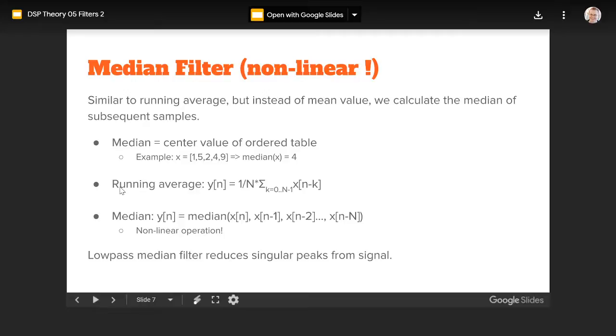Then use a high-pass median filter, meaning you take the original data and subtract the median filtered one with the correct time shift. The only things remaining are those spurious peaks. That's also a nice trick. But again, it's about what you're trying to look for in the data. If it's single anomalies you're looking for, the median filter is probably a way to find them.